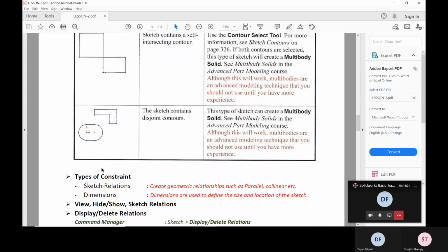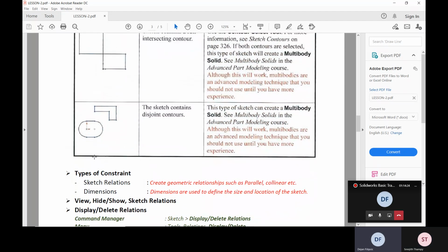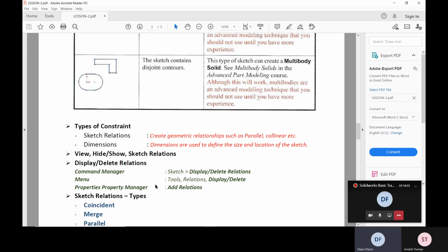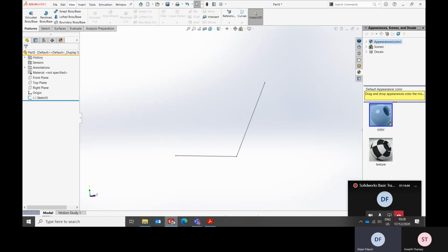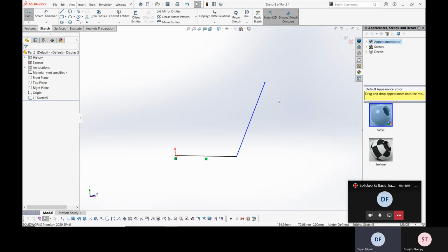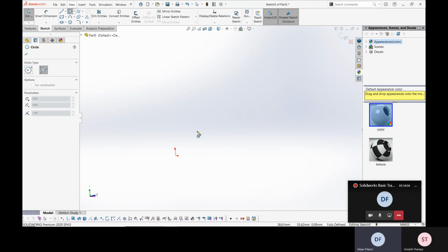So for all the lines we create in sketching, you have two types of lines, two types of features if you want. Sometimes when you sketch, you want to have some reference lines, and you can have those. You can just click on the line and call it construction geometry. When we do a sketch and want an object extruded, those are not necessarily the only lines we have in the sketching module.